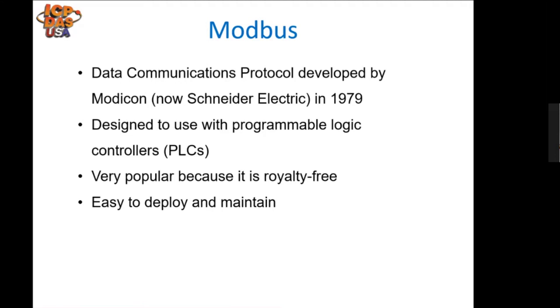Modbus is popular in the industry environment because it is openly published and royalty-free. It was developed for industrial applications. It's relatively easy to deploy and maintain compared to other standards. The Modbus protocol uses character serial communication lines, Ethernet, or the Internet Protocol suite as a transport layer.